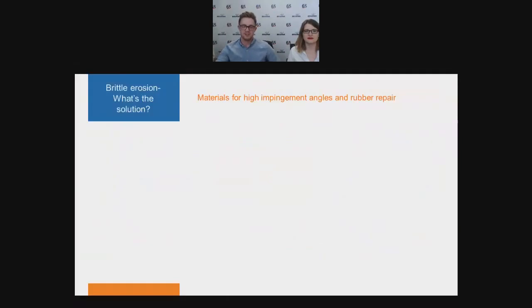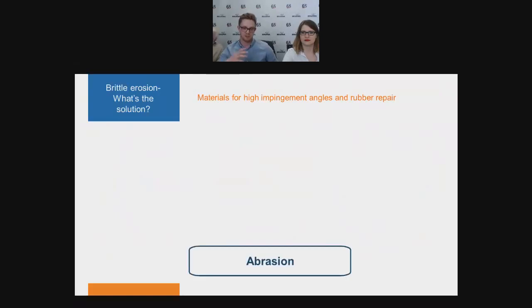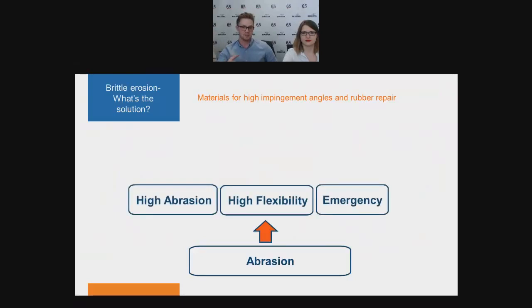Okay, so we've just seen a video that shows some of our products that we use in the case of ductile abrasion. So for the case of brittle type abrasion, because of the higher impact angles, remember up to that 90 degrees, the elastomeric type products are frequently specified. These harder elastomer rubber-type materials tend to absorb the impact forces and then deflect the impacting materials.